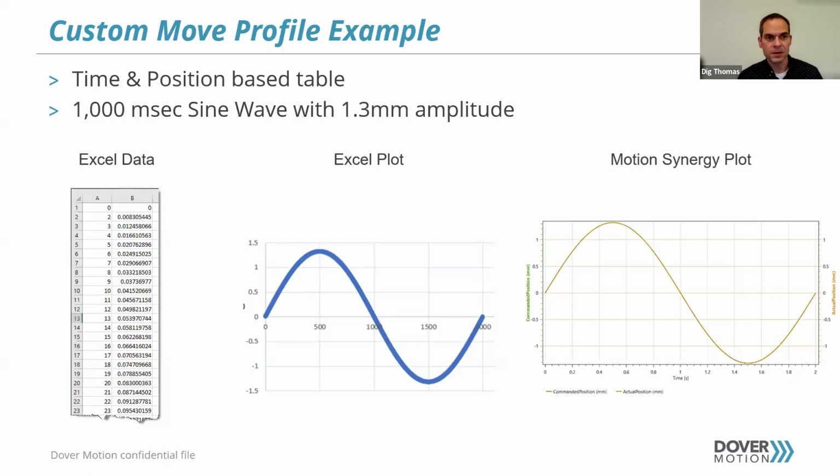Another example, somewhat simpler, is the single axis version. Basically, the UDP is looking for some sort of time input, or a tick or a pulse, that can be generated internally, but can be external as well. From the internal point of view, you can put in whatever arbitrary table you want and generate that type of move on a single axis.